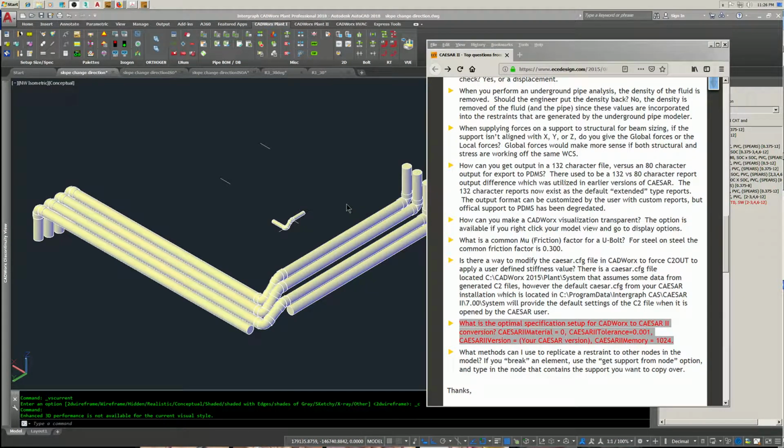This video is going to be how to connect slope lines with differing elevations and a change of direction. First, I want to show you what I found here on tolerances for Caesar 2 pipe stress analysis. This is what they recommend, and I've been using 5/1000ths of a millimeter.